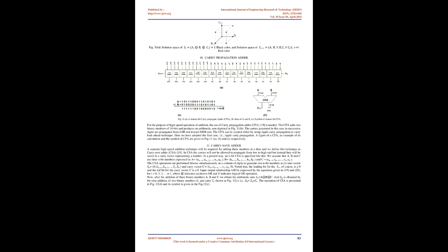The threshold gate-based implementations of the Boolean logic gates have the same basic circuit topology, as we will draw in the subsequent sections. The threshold gates consist of a bias capacitance, a tunnel junction having capacitance, and an output capacitance. The AND and OR gates contain two input capacitors. For both the AND and OR gates, the two input capacitors are C1P equals C2P equals 0.5 for positively weighted inputs. On the other hand, for the NAND and NOR gates, the two capacitors hold the values C1N equals C2N equals 0.5